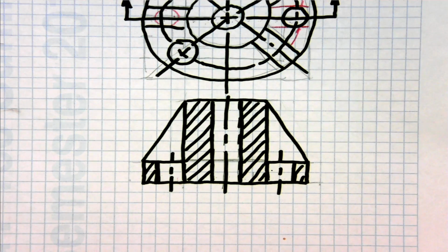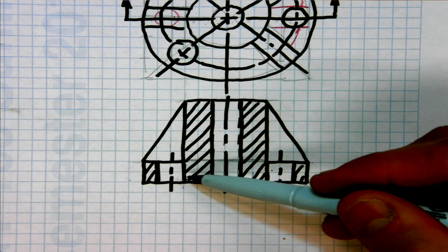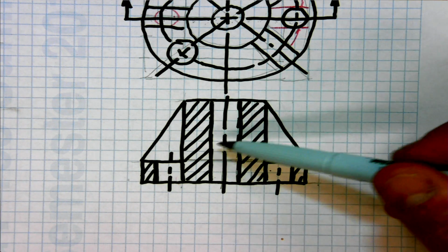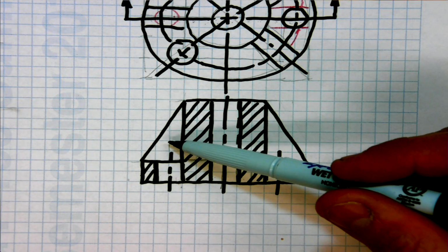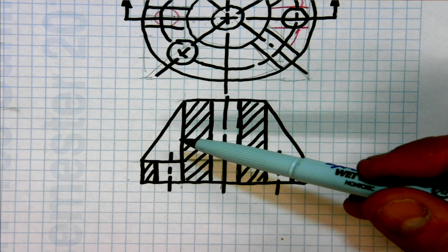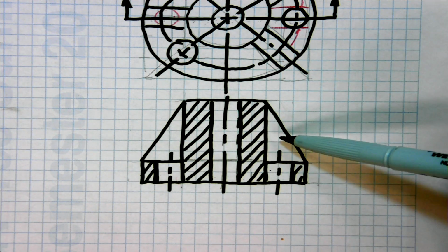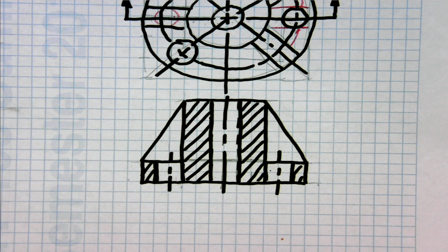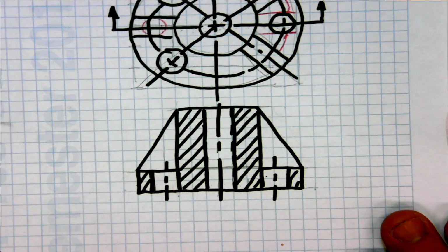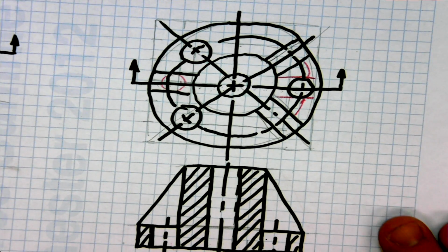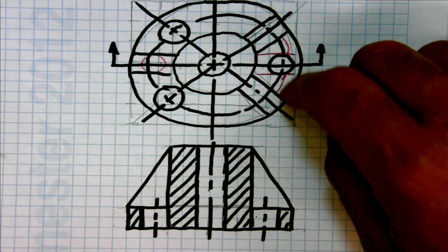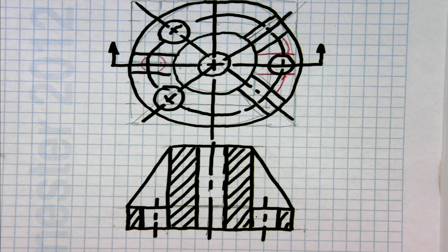So there we have the resultant view. The holes have been rotated. These two ribs have been rotated. Okay, showing you then material here, the rib is material, but it's not crosshatched to keep it from being confusing, because that would make it look as if it's a full conical part, but it's not. It's just support features. So there's two examples of full sections. Again, a cylinder with these support ribs and the holes in there revolved into position.